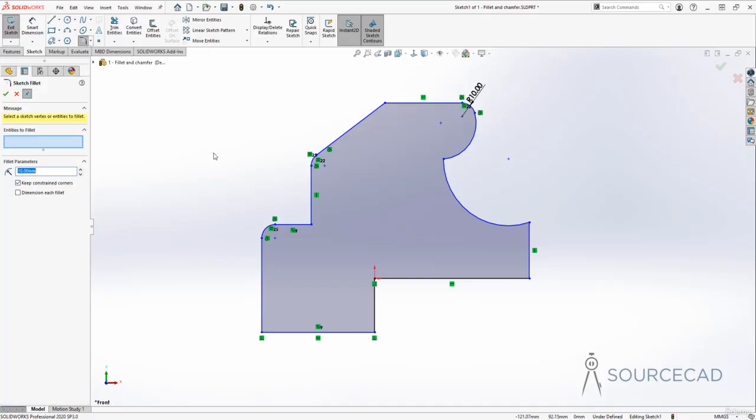All right, let's make it again. So I'll go to fillet, and once again, I'll make selection, but now I'll make it in a different way. So I'll just make a window kind of like this, a big window. And here you'll notice that all of these edges which are inside the window are now selected. So if you want to make a quick selection, you can do this using this kind of method.